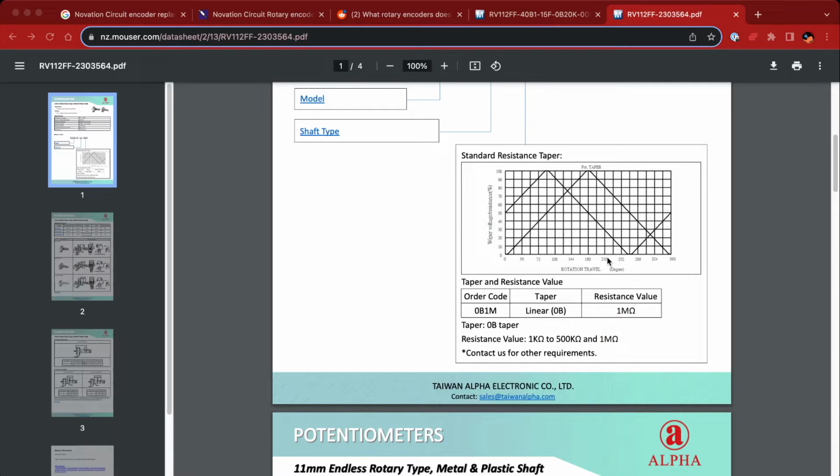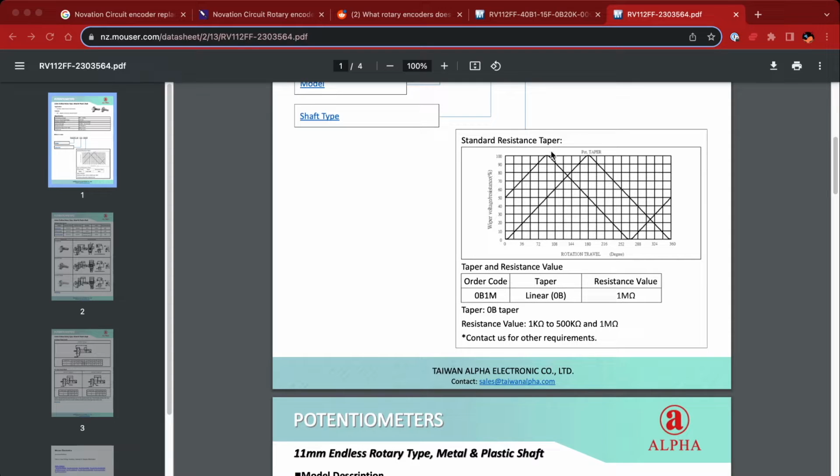Of course, this could be problematic, because if we're trying to determine direction, we won't be able to. If we say direction is going this way when the previous value is lower than the next value, that logic doesn't hold true once we get past that 180 degree point. It becomes the opposite. And so that's why we use that second wave here.